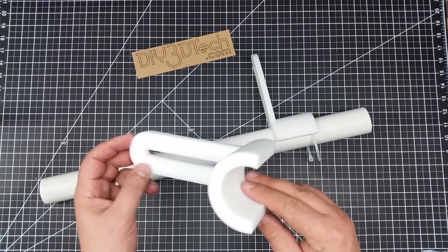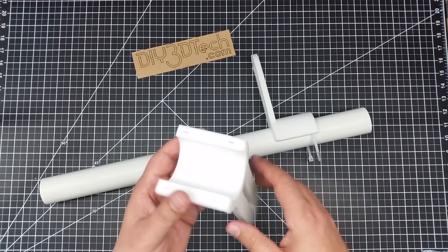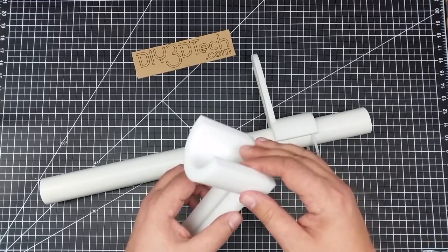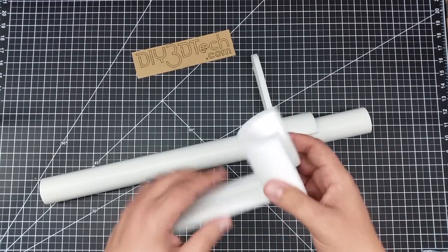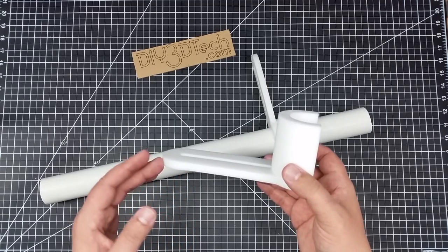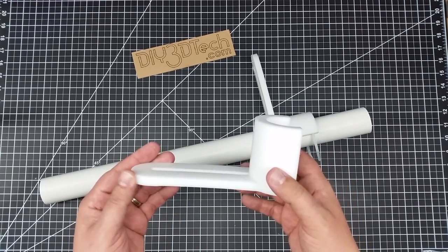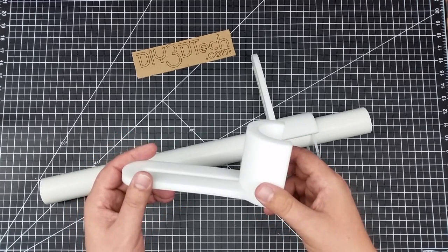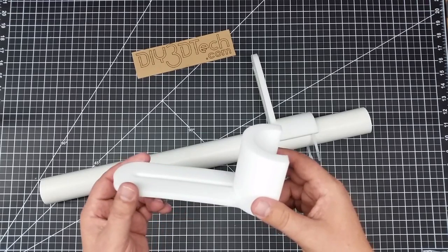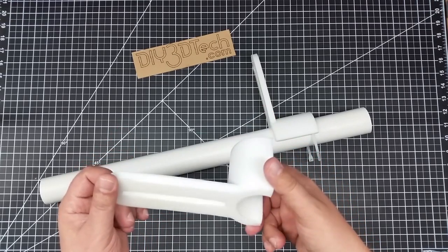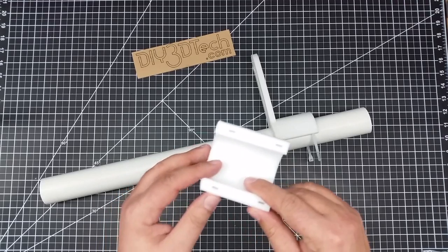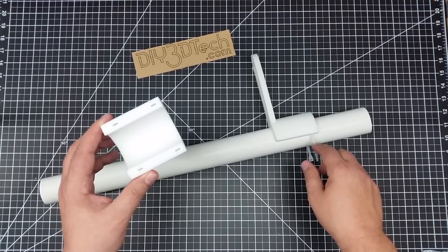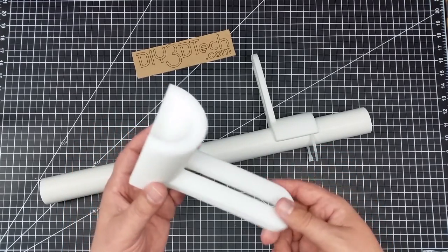Got real good adhesion. I had done some homework on the internet, and some folks were mentioning that they were having some issues with layer adhesion at lower temperatures, but when they got up into the 240 region, things seemed to be good, and the same with the bed temperature. So 110 degrees on the bed, 245C on the hot end seemed to be the real trick for this. Printed with no supports, even with the zip strip holes, and you can see I got a zip strip actually in one of them down here. It came out pretty good.